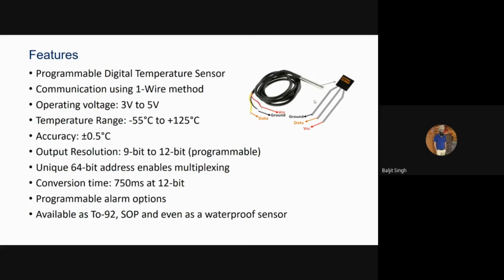The order of the sensor, which we study in control systems, gets increased whenever we use this housing outside a sensor. Otherwise the temperature sensor is a first order device, but due to this kind of housing it becomes a second order device, and accordingly its time response increases somewhat.